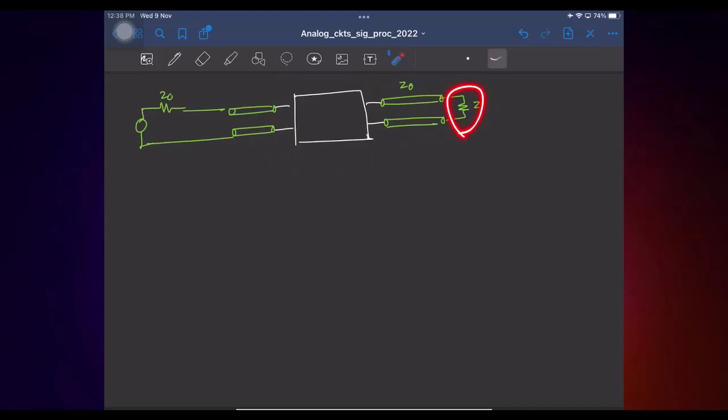But this is at least simple. What you're saying is absolutely right. Now this no longer is a short. But at least now, if this has a characteristic impedance Z0, and this is Z0, what is the looking-in impedance? It is Z0. So it is as if I put a Z0 right at the end of the chip, right? This you couldn't do with short circuits, right? And similarly, here also again looking in, it looks like Z0, as if you have terminated these 2 ends with Z0. Fine.